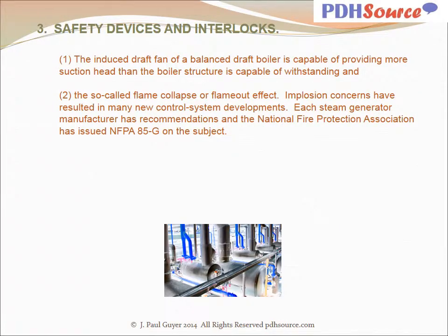First, the induced draft fan of a balanced draft boiler is capable of providing more suction head than the boiler structure is capable of withstanding. And second, the so-called flame collapse or flame out effect. Implosion concerns have resulted in many new control system developments. Each steam generator manufacturer has recommendations, and the NFPA has issued NFPA 85G on the subject.